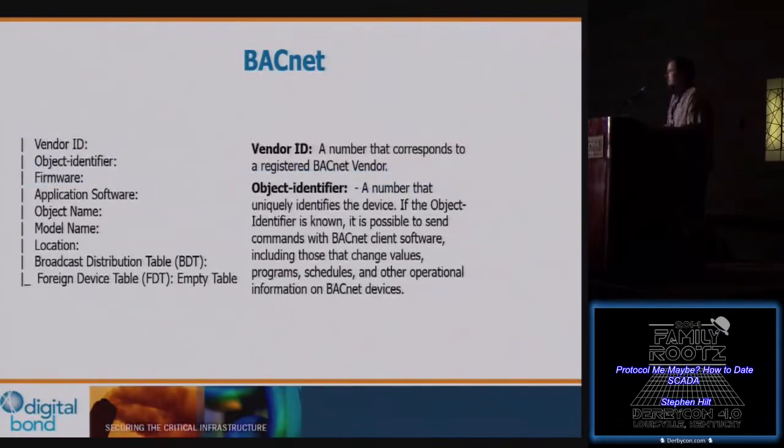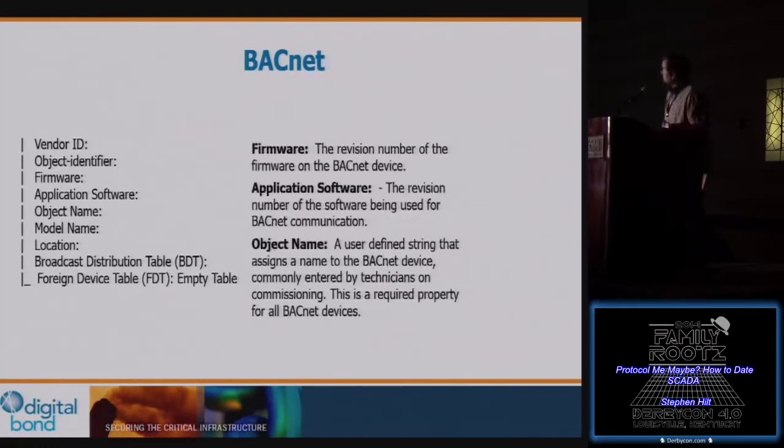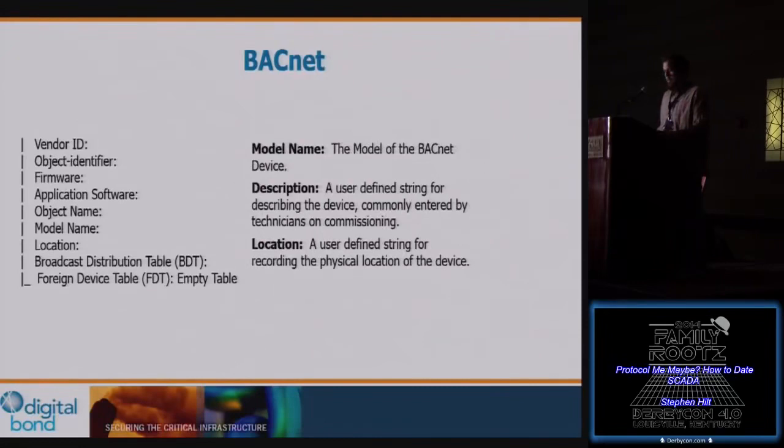after several iterations of a Python script, to pull vendor ID and object identifier, which is the number, as I stated earlier, that uniquely identifies that device. If the object identifier is known, it is possible to send commands with BACnet client software, which is important. Take note of that one. You know, the firmware, application software, object name, model name, description, location, which is usually a user-defined string.